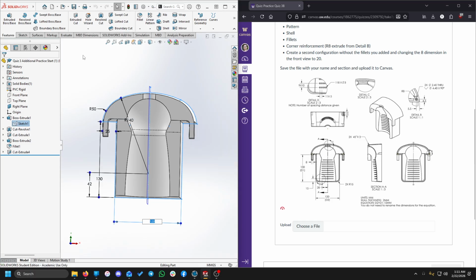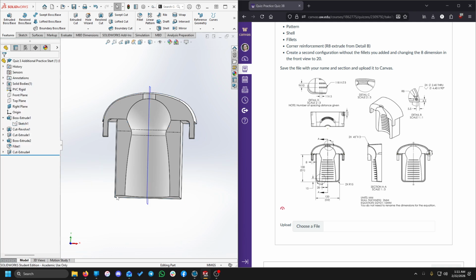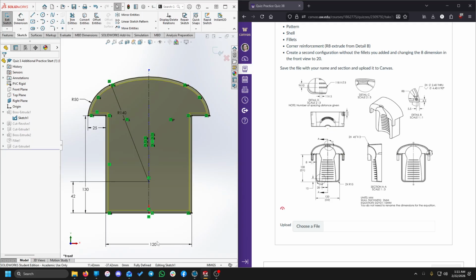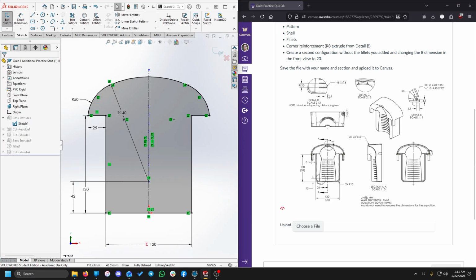Never hurts to update everything to the modern version. Well, it can hurt, but in SOLIDWORKS it's fine. So, setting this up, I'm just going to do the equation through the little menu here. Usually it would let me do that. There we go. So the 120 is equal to the 130 minus 10 millimeter. Check mark. Oh, there's our equation out of the way.